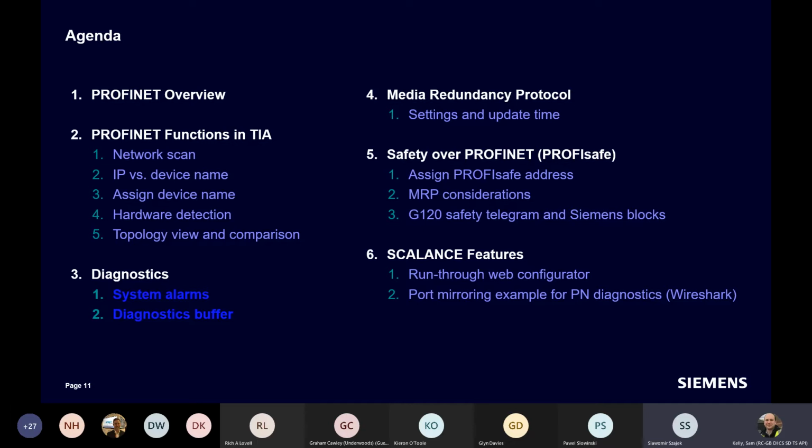You can see, yes, I'm sending the output high to drive the lift, but it's interlocked with a gate, so we can see that the gate signal is low, therefore we're not able to drive the lift. So that's something you could have on the HMI panel to give you that type of information. Is that something that would perhaps be of use?